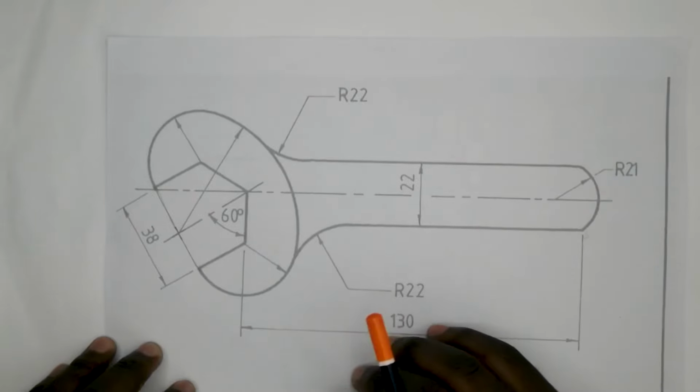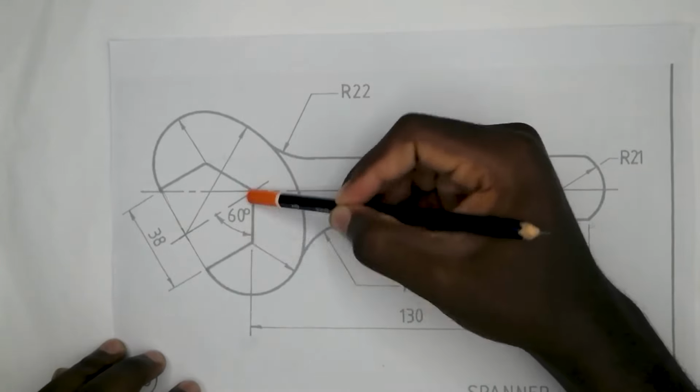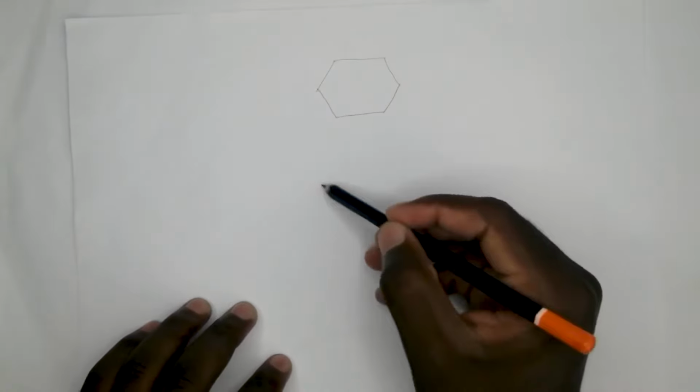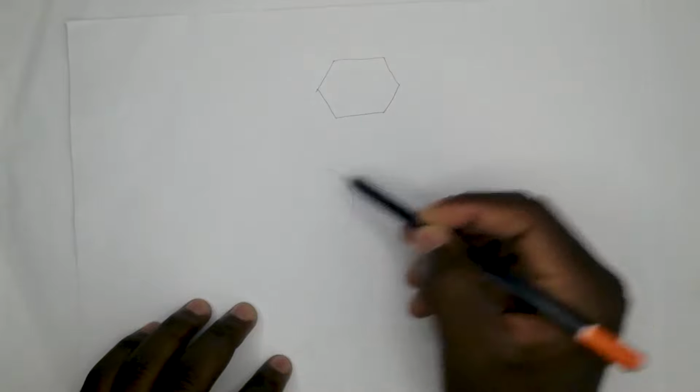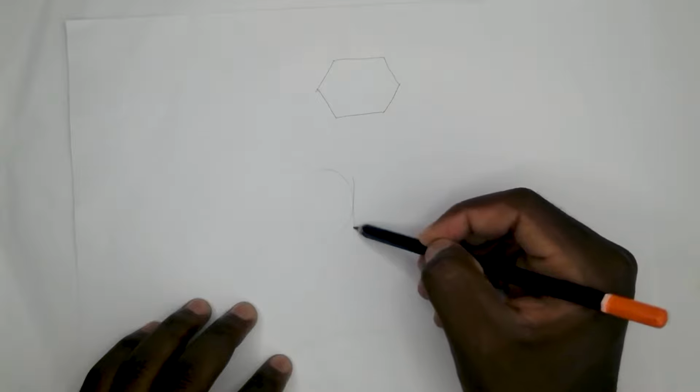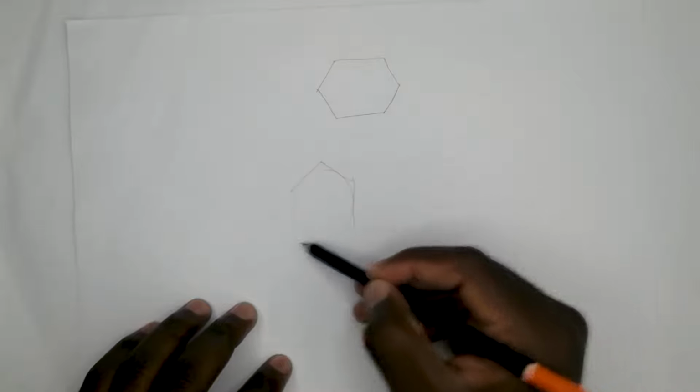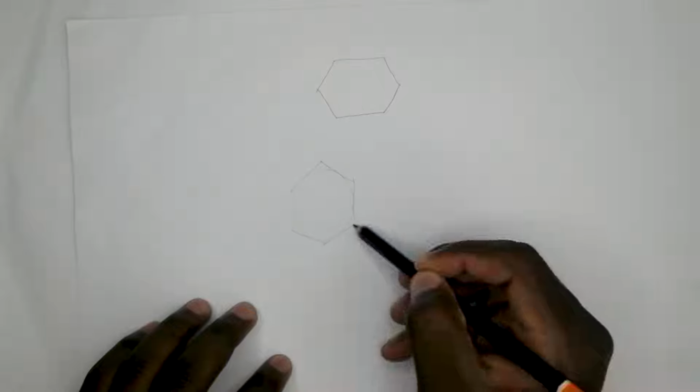After we have drawn this circle, we need to draw our hexagon using the method of distance across flats. The most important thing here is looking at the orientation of your hexagon. You can see that it's got its flat sides here and there. I'll try sketching that so that you can actually visualize it better. We've got a circle like this, and then we have our hexagon. In full, it will look like this. This is how it should look.